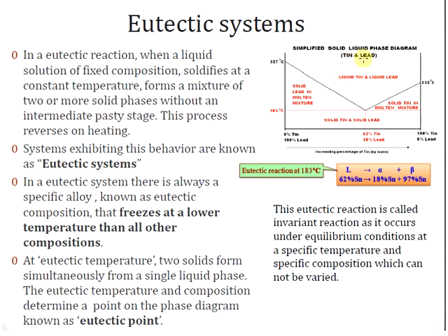So on this side you see the liquid phase, liquid tin. A specific example, one of the most important specific examples for the eutectic reaction, is tin-lead. This is the particular alloy which is used for soldering. For soldering we use this particular alloy, tin and lead, at a particular combination, and that corresponds to the eutectic point.